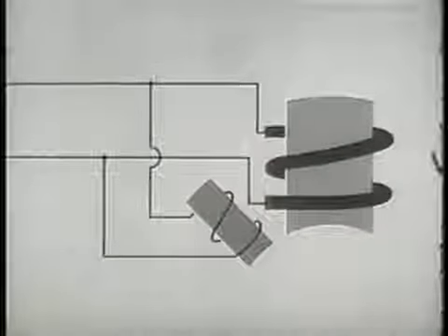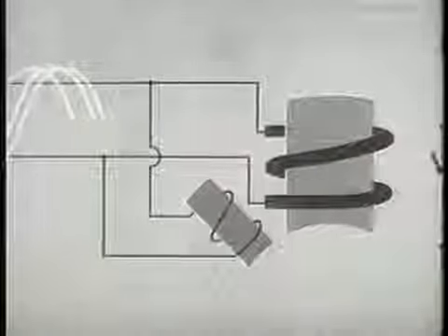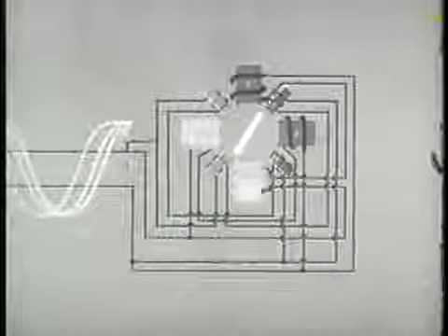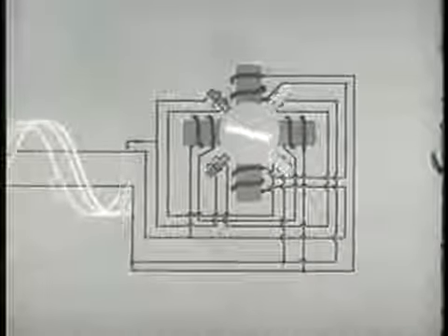We now have in effect a two-phase current. The phase difference causes the starter windings to be energized before the main windings. Magnetic fields are formed progressively. This is called a split-phase motor. The magnetic field now rotates electrically. The basic requirement of relative motion has been satisfied and the motor has been started.